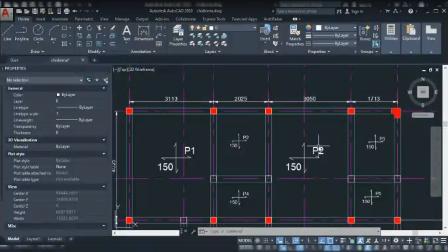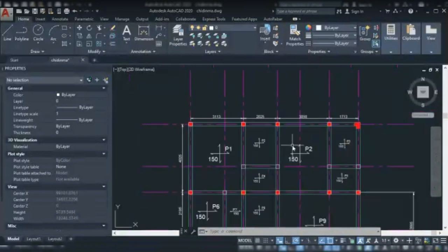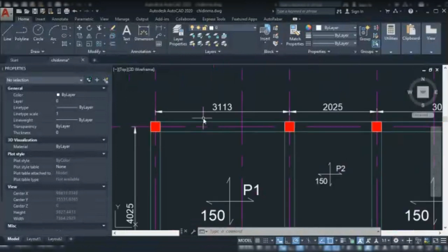So even when you use 400 as the depth of your beam, it still carries your structure. But we are going to make the assumption of taking 450, since it's what everybody uses, to be on the safer side. So we make use of 450 as the depth of our beam. The width of the beam, you always take the size of the walls. So we'll be taking a size of 225.